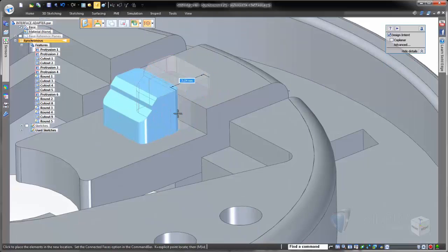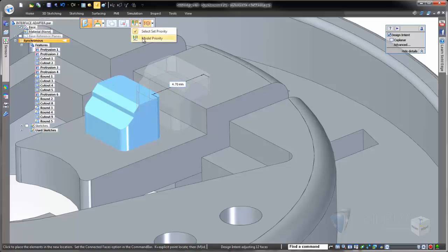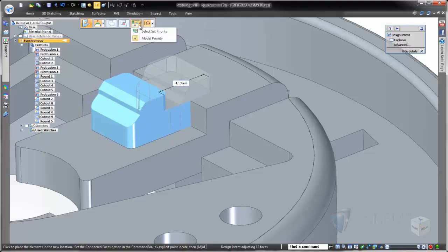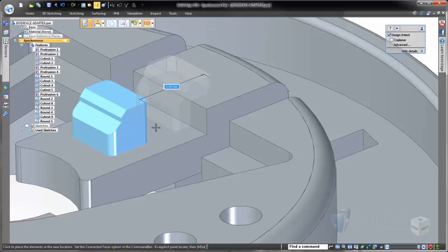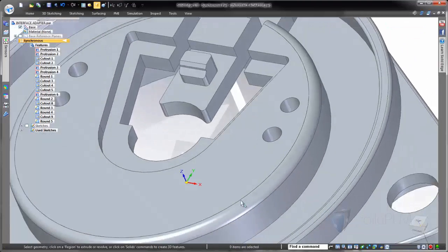There's also been a lot of great improvements to enable dragging features that cross over stepped faces to react as a separate set of geometry. Solid Edge will no longer automatically extend those faces, but this, of course, is optional in the quick bar options that you see here at the top.